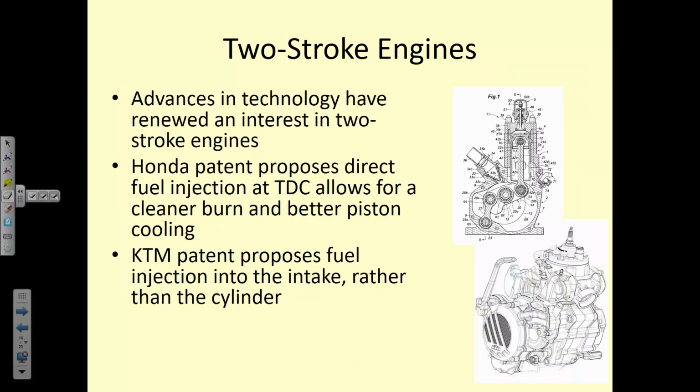However, there have been a couple of recent upticks in the use of 2-stroke engines in motorcycles, and both Honda and KTM have patents in the works in just the last couple of years that are pretty interesting. With the Honda patent, they have their fuel injector here, and the idea is to spray the fuel onto the back of the cylinder, rather than having the fuel injectors at the top where the venting happens to the side.